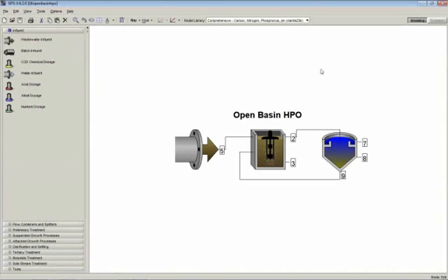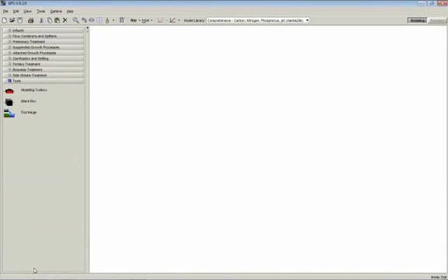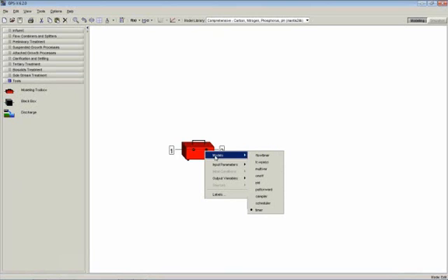Okay. I'm going to just touch on our new toolbox models as well. So if you drag a toolbox object onto the screen, you may remember that we have a collection of other little tools that we use in GPSX to make the plant work in the same way that it does in reality. So this is places where you would find controllers, on-off controllers, PID control loops. This is where a PID forward, P-forward loop is. You have a sampler here that you can set up in your layout to act like a real composite sampler.